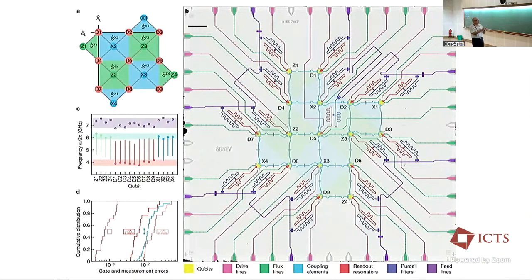And if I were giving a talk about this, which is not my work, I would be telling you about qubit couplers. Well, I would first back up and say some of these are ancilla qubits and some of them are data qubits, and they're used to achieve an error correction experiment. And there are couplers between the qubits that actuate 2 qubit gates that enable entanglement.